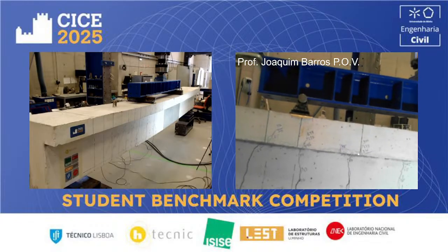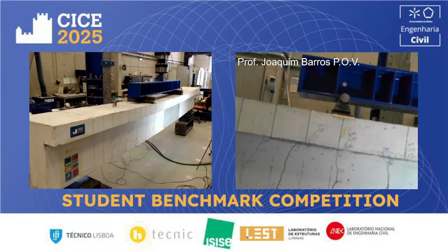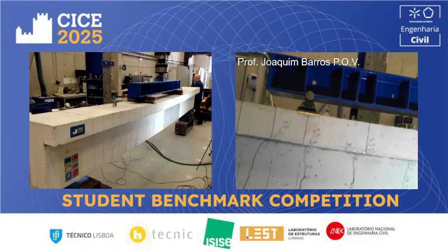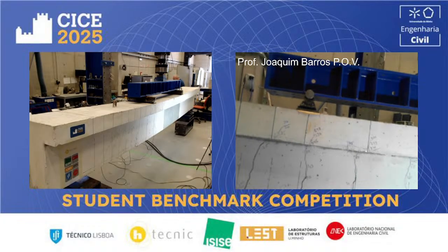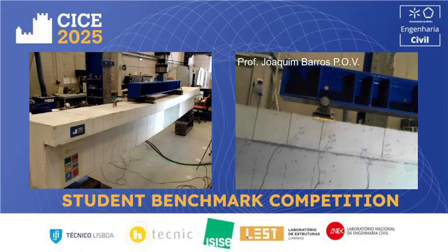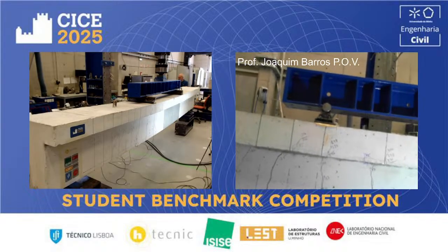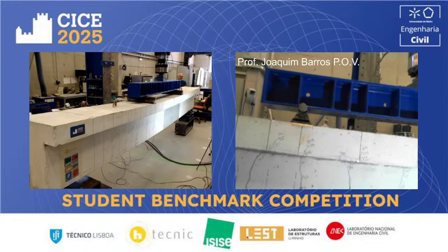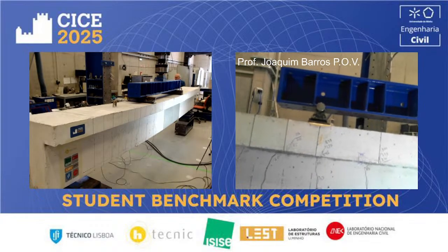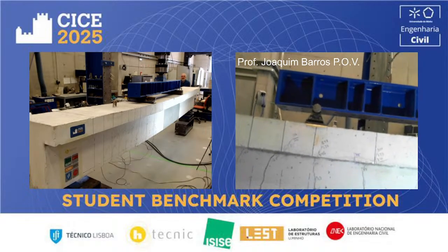It will be very interesting to verify the capacity of this more sophisticated approach to predict the average crack spacing. Because if we do not predict the average crack spacing with sufficient rigor, then the model obviously will not be able to determine properly the tensile stress in the reinforcements. But we will have the opportunity to analyze the predictive performance of this approach, not only the one that we have in FIB, but also in the other standards.